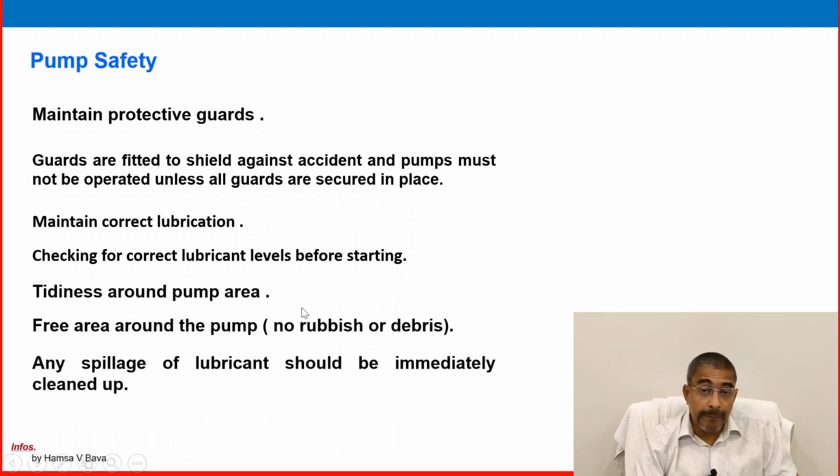Tidiness around the pump area is very important. After any mechanical work or other maintenance work, cleaning the area and hygiene are important. Safety housekeeping is also important. Keep the area around the pump free of rubbish and debris. Any spillage of lubricant should be cleaned up immediately.